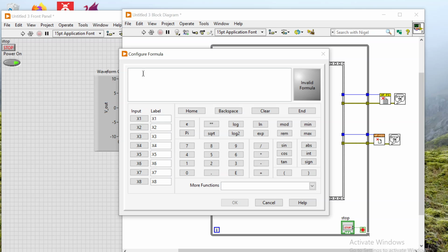So in the slides that we have for this lab, you have the equation for the output voltage of a voltage divider. V out is equal to the supply voltage, Vs, times R2, which is the thermistor resistance, divided by R1 plus R2. And then what you need to do is do some algebra to get RT on the left and all the other variables on the right. So the other variables we know are going to be the supply voltage, we'll say Vs.